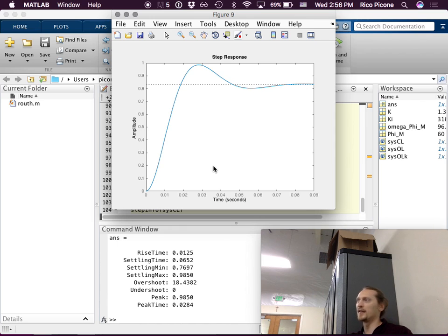You could just add in an integrator, and you would improve the steady state situation. You could just do that ad hoc if you want to, or you could design it based on a lag. And there's a lag design example in Nyquist if you wanted to look at how they do that.